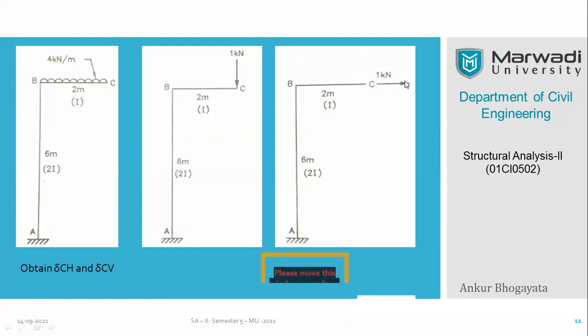Based on the application of the forces, your M1 and M2 will be different equations, because moments will be different for segments B to C and C to A for vertical force and horizontal force. However, there will be a common equation available to every segment in terms of external load. So capital M will be the same, but M1 and M2 will be different, right?